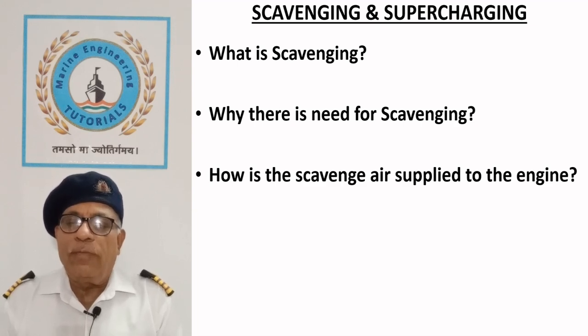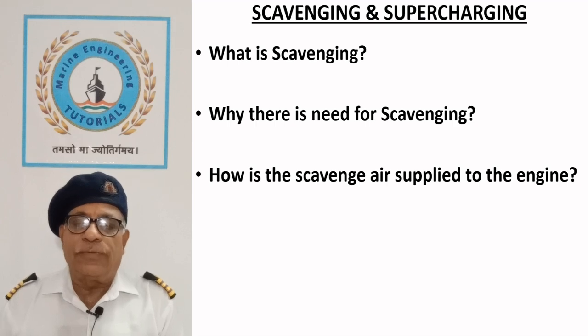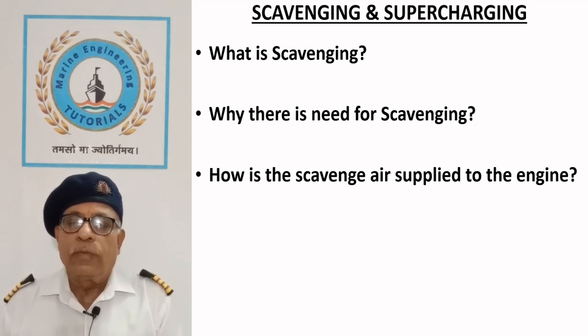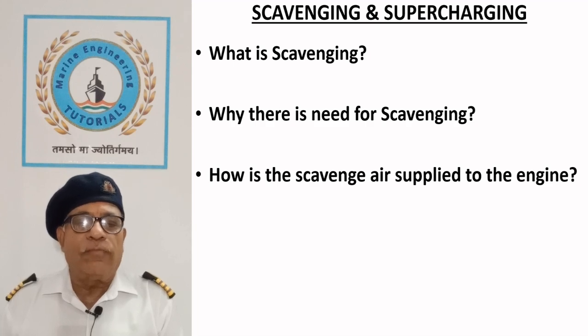Compression of air is associated with a rise in its temperature and reduction of density, which is responsible for low power output from the engine with a corresponding rise in exhaust gas temperature, causing burning of the exhaust valve and seat. The charged air is thus cooled to reduce its temperature before it enters the diesel engine cylinder.